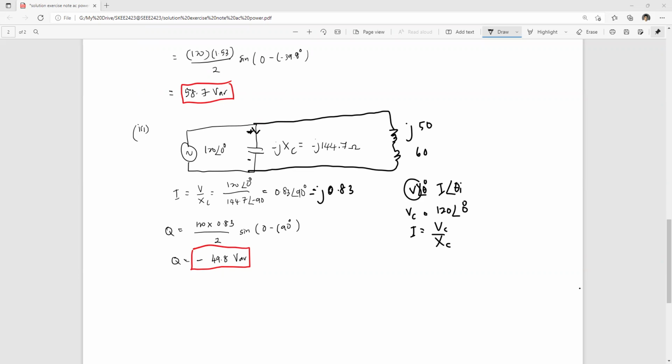And what about the reactive power? The reactive power Q is equal to V RMS times I RMS times sine of 23 degrees. Based on my calculator, the value of your Q is 1.089 kvar. So I think that solves example 4. Let's look at example 4b.